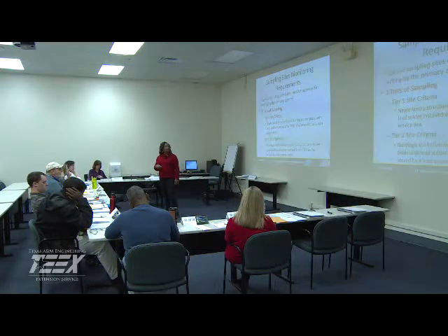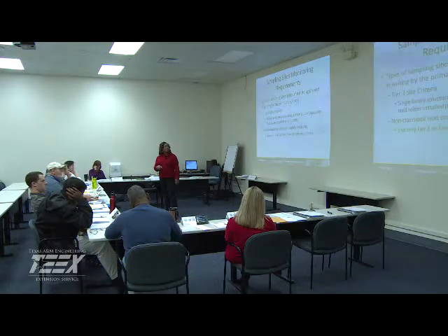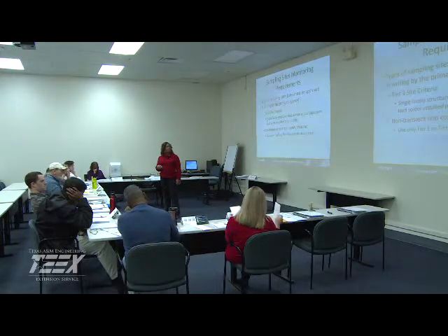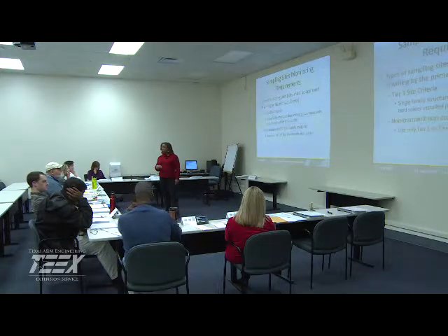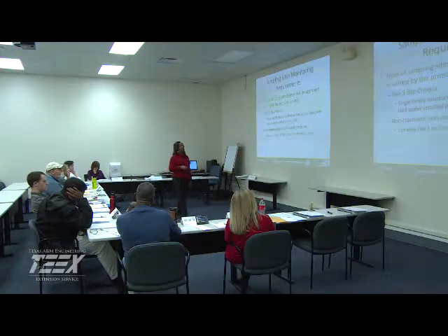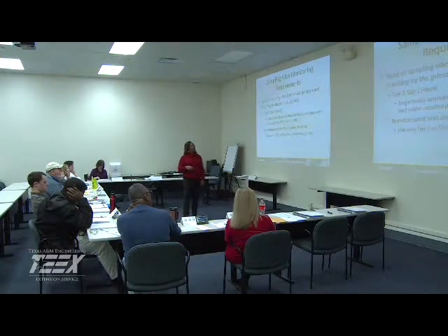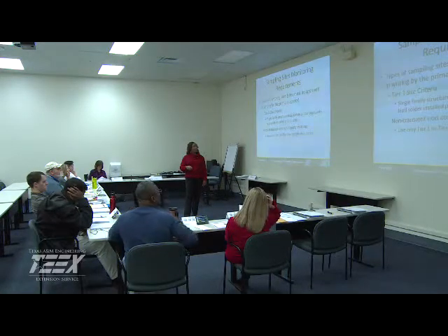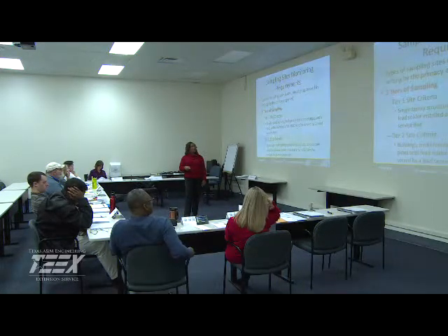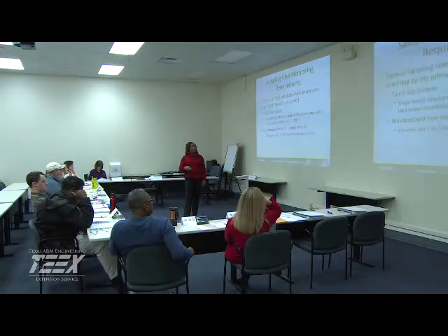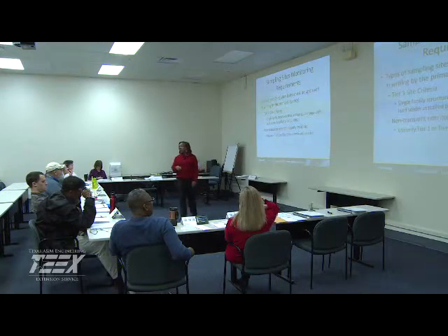And Tier 3: single-family structures that contain copper pipe, lead and solder installed prior to 1983. So those are my 3 tiers for representative sampling. For a non-transient, non-community system, I can only use Tier 1 and Tier 2.